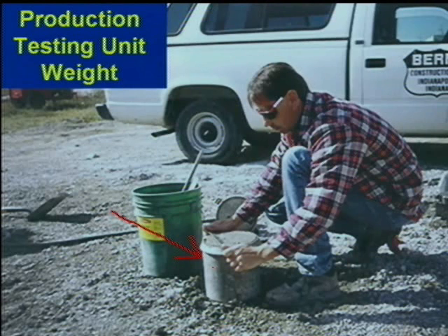In the homework problem that you just finished up, you notice that it didn't come up to be what we expected it to be. It's a little bit short. That 2%, all right, frequently is going to be traced back to an issue with air or an issue with specific gravity changing in your aggregates or too much water being in the mix. There are things that you can do to track this.